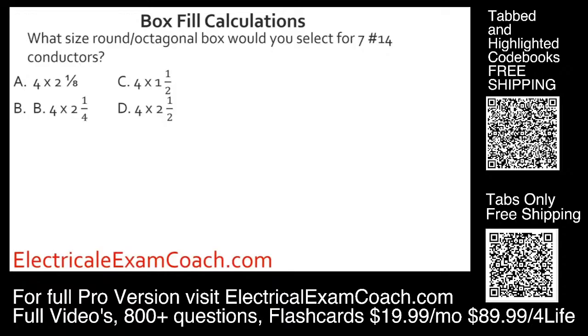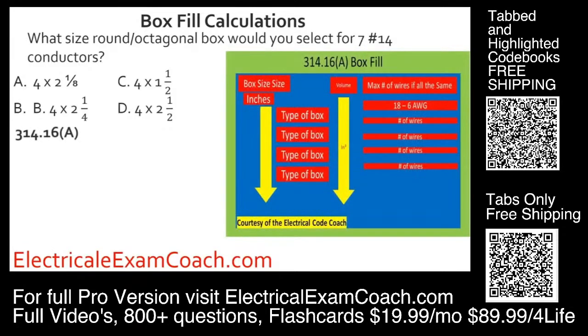What size round octagonal box would you select for 7 number 14 gauge conductors? We're going to head to table 314.16(A). We're going to start here on the right hand side and find our gauge wire. Then we're going to come down and find a box that fits it, and be sure when we cross over that we stay in the right category of box, and we're going to select C.